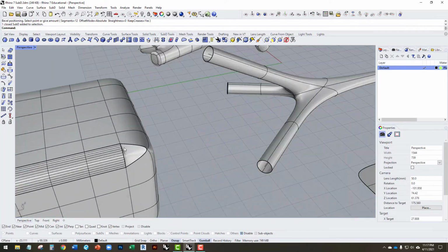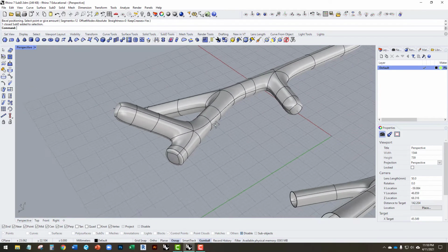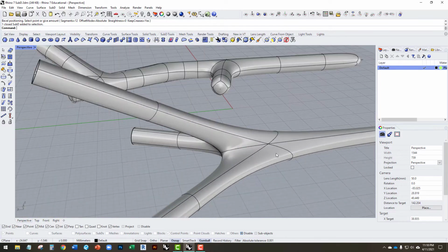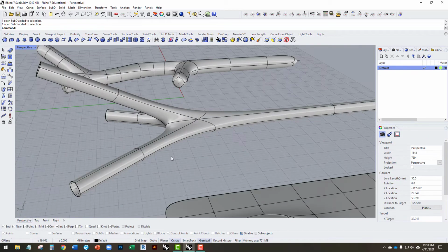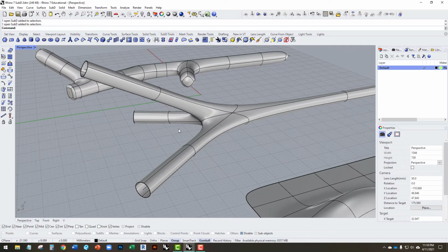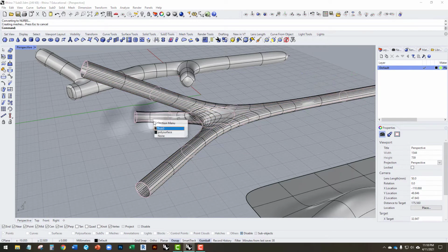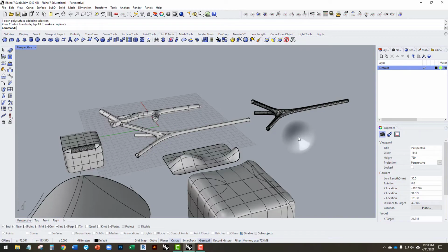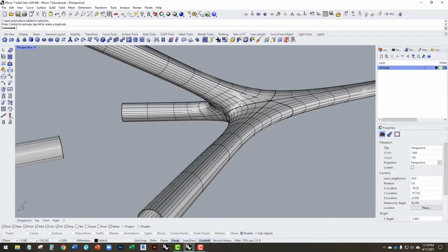All right, so that's Bevel Edge. And once we're done modeling, and let's say we want to turn this into a poly surface, something that we can manipulate or bring back into other types of geometry in Rhino, we can select it and hit Convert Object to NURBS. It'll ask for some options, and then you'll notice we now have a poly surface. So this could be useful if you're running a Grasshopper script that requires a poly surface or a surface.